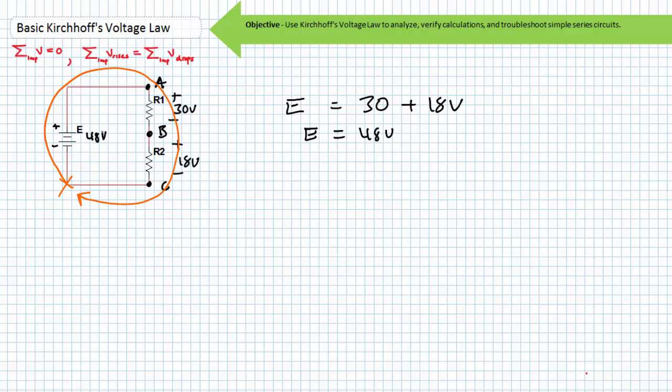Now, let's add a ground reference node to this circuit and see if this in any way affects the functionality or KVL analysis of this circuit. Some of you may be groaning and slapping your forehead, saying that's not where I expected the ground reference to go. This placement of the ground reference on the positive terminal is of no concern to you. A circuit still exists and KVL can still be applied.